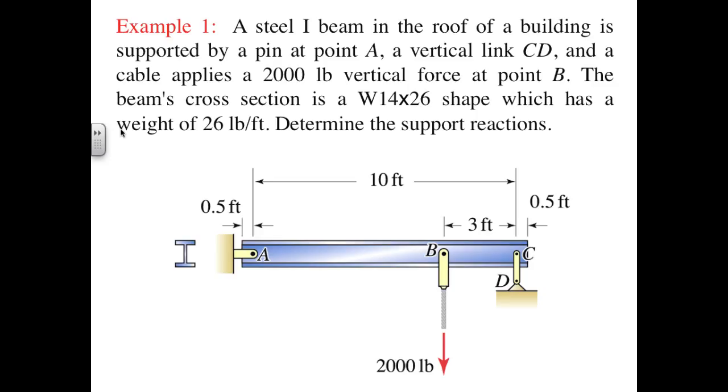On the left side, we have a short segment built into a wall and then pin supported at A. The fact that one side is not pin supported but built in means we are unable to identify this short segment as a two-force member. When we separate the I-beam at the support at A, we need to represent the reactions as two force components, an AX and an AY component, consistent with the pin being unable to move through its bearing.